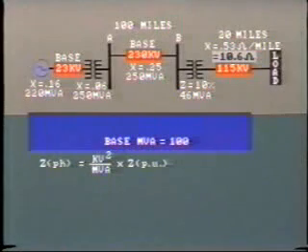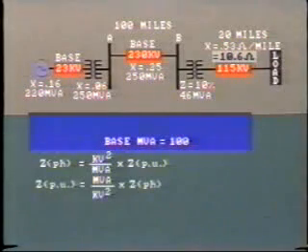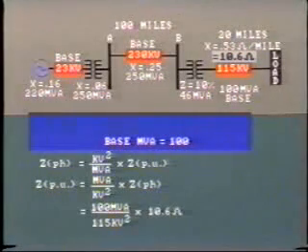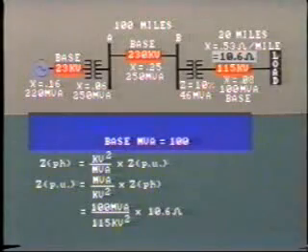We already learned that ohmic impedance is given by the expression impedance per phase equals kV squared divided by MVA times per unit impedance. Transposing this, we find that per unit impedance is equal to MVA divided by kV squared and multiplied by the ohmic impedance. Using a power base of 100 MVA, the per unit impedance for the 115 kV line equals 100 MVA divided by 115 kV squared times 10.6 ohms equals 0.08 per unit, or 8%. It is extremely important, whenever quoting per unit impedance values, you must always include the associated value for base MVA.